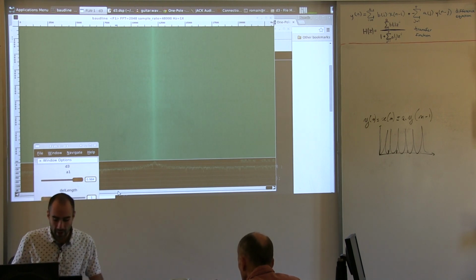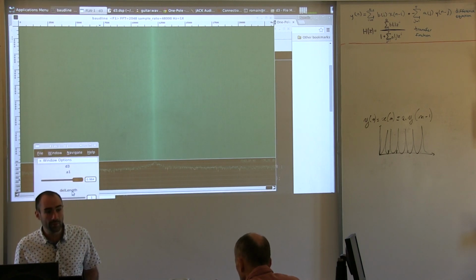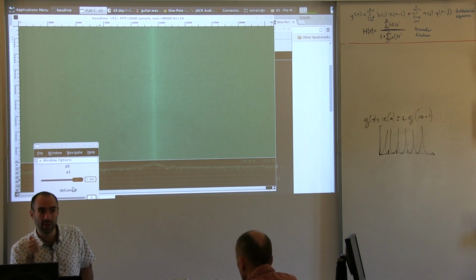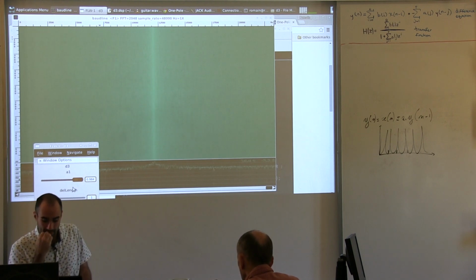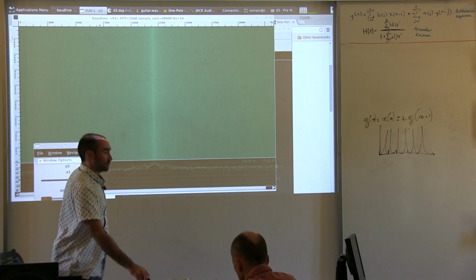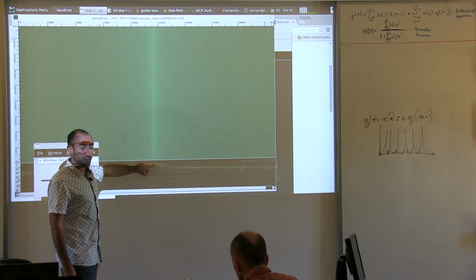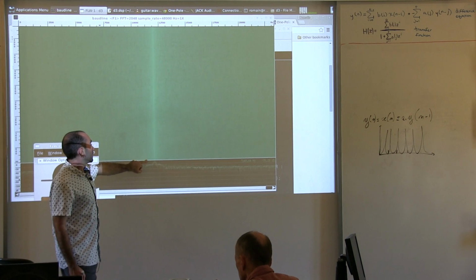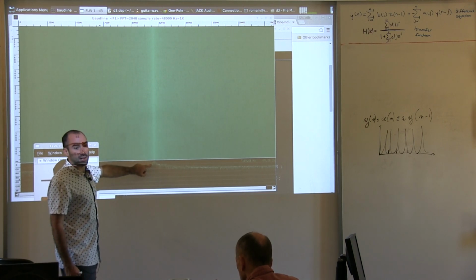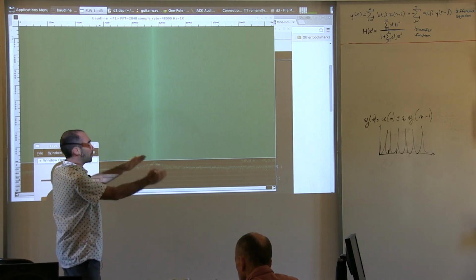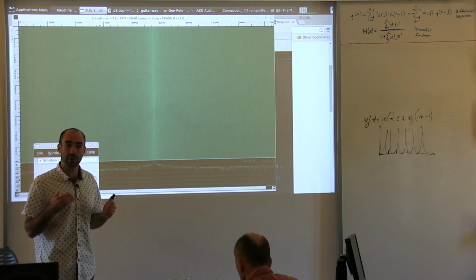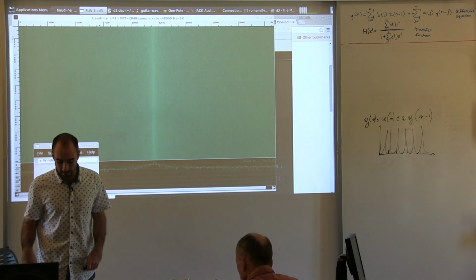Okay. So what happened here is we have a one sample delay that adds to the one sample delay that we already have and that is implied by the feedback, right? And I can totally see that there is a peak here now. So it means that that's basically the first tooth of my comb filter that was moved here at the center of the spectrum, or like halfway between half the sampling rate and 0 hertz. Okay.